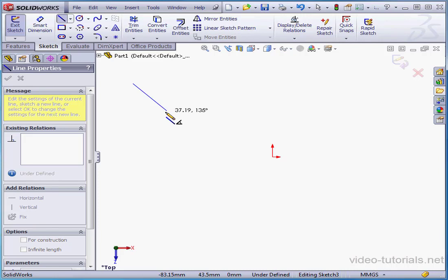Let's left-click to place the first point of the line. You can release the mouse button. Notice this rubber band effect. Next to the cursor is a feedback number, and what this does is give us an approximate length of the line in your current units of measurement. In my case, millimeters. A left click now would give me a 24 millimeter line. Let's move a little bit more. A second left click places the second point of our line.